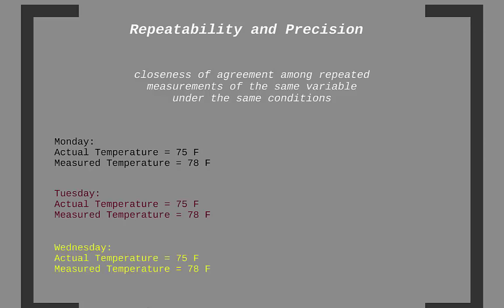Well, 78 degrees Fahrenheit is not 75 degrees Fahrenheit, so the sensor is not accurate per se, but the outputted values from the sensor that come from measuring the same value are all the same. Thus, the sensor is said to be precise. This may be counter to what you had previously thought precise meant, but I assure you this is how they define it in the controls industry.